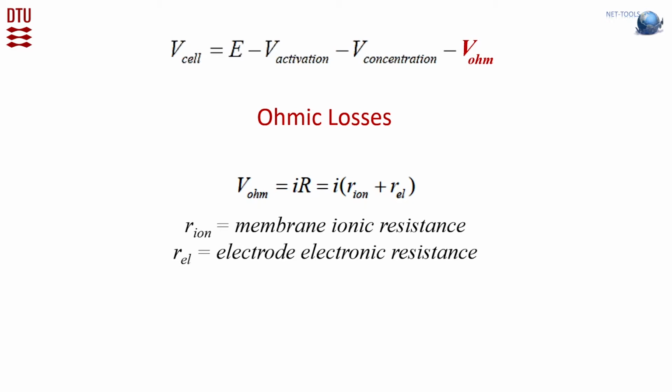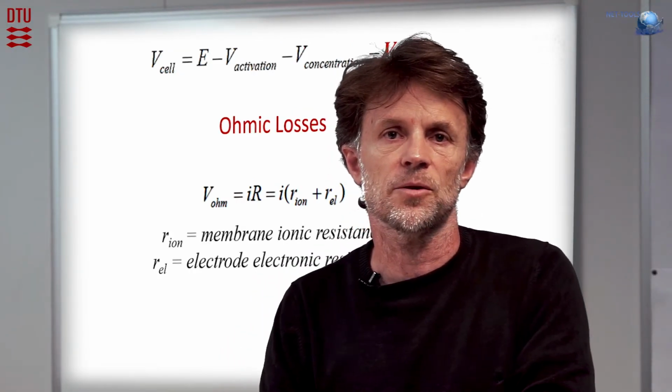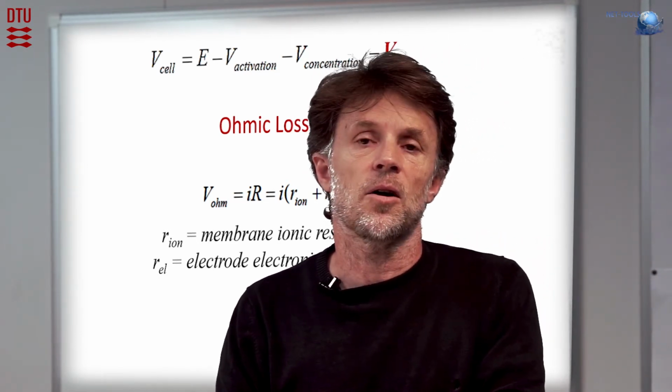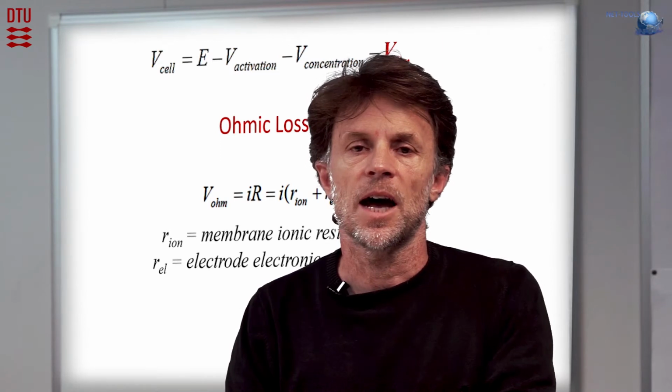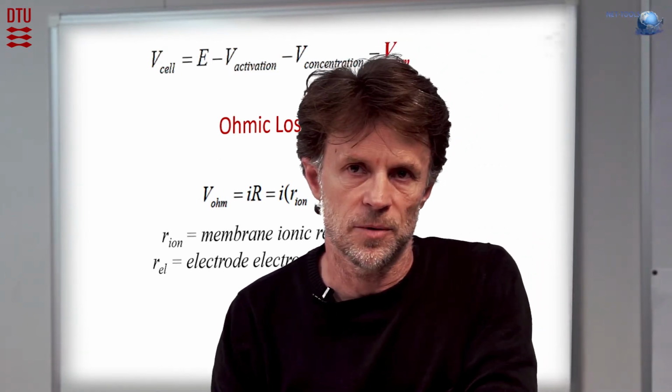How to reduce these ohmic losses? Well, the use of electrodes with the highest possible conductivity is of course welcome. Good design and use of appropriate materials for the bipolar plates or the cell interconnects is also crucial. Another way is to make the electrolyte as thin as possible.